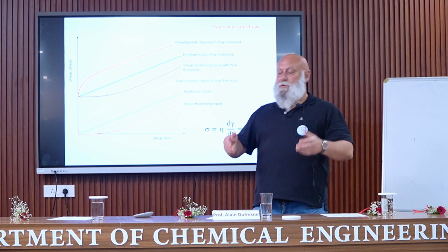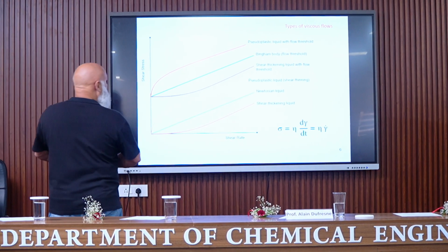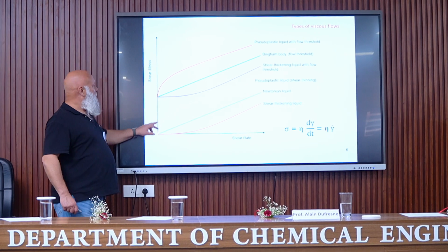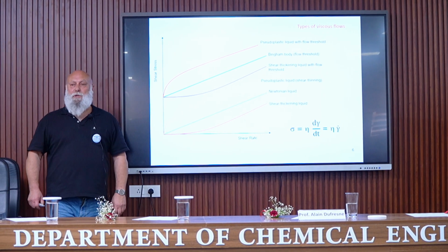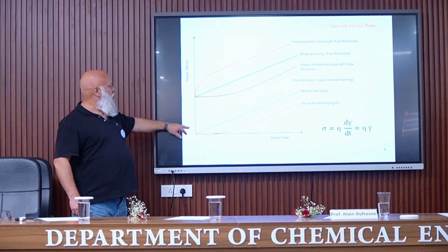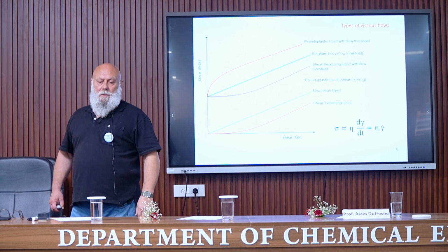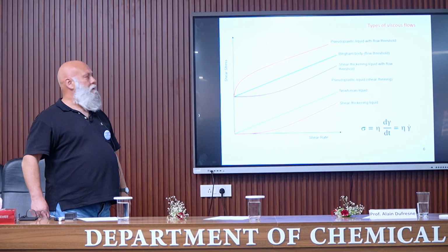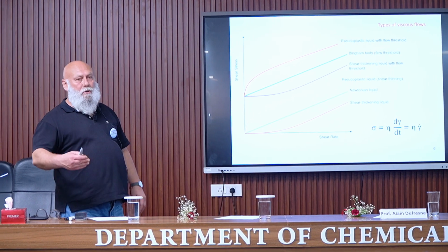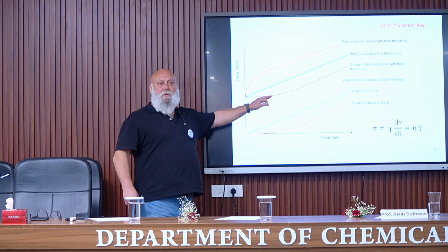And we can have also what is called a Bingham body with different behavior. So for a Bingham body, you can see that it's necessary to apply a threshold or critical stress in order to observe the flow of the material, sorry, of the liquid.